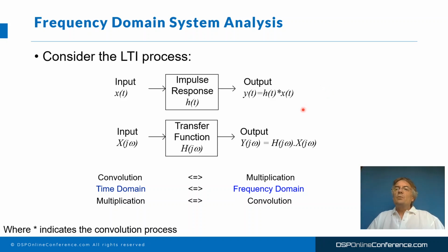So now, if we think about this, we have a trade-off. The direct path requires a lot of MIPS and memory. The indirect path requires that we take an array of data, we convert it to the frequency domain, we then do our very simple multiplication, and then we pass the data back to the time domain using the inverse fast Fourier transform. And now we get our output.